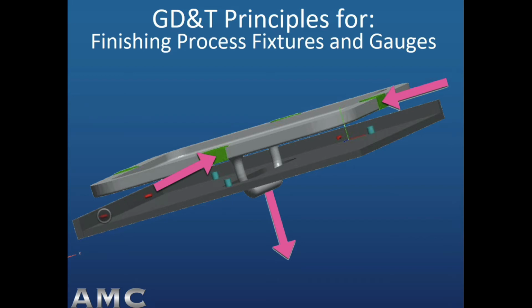As long as the pins touch the casting on a drafted surface at the same elevation, we learned in part 1 that draft is really an offset and a draw length. And if you touch that draw length at the same elevation across the drafted surfaces, then the casting will sit reliably against those pins and it's an accurate location. Draft doesn't really interfere with accurate location if the pins touch at that same elevation, based on the offset versus draw length of a draw angle.